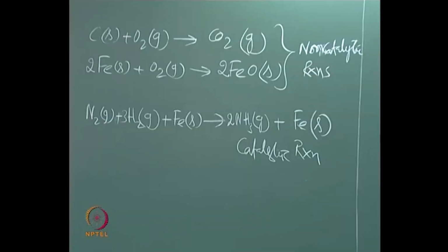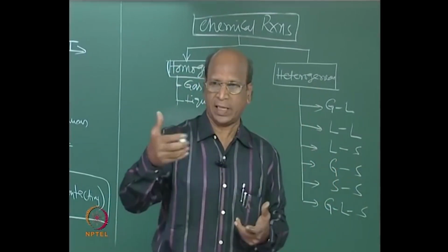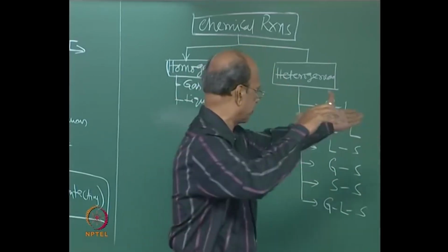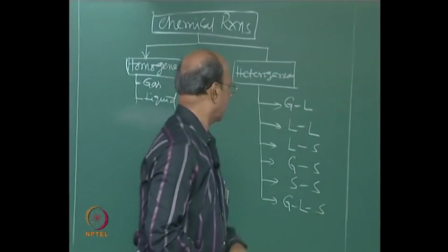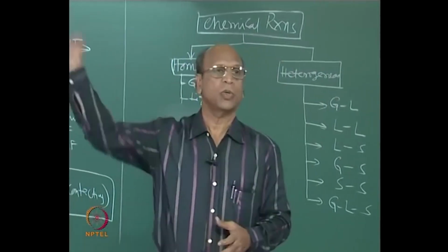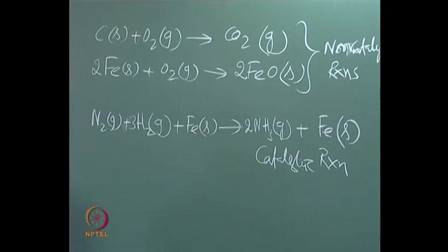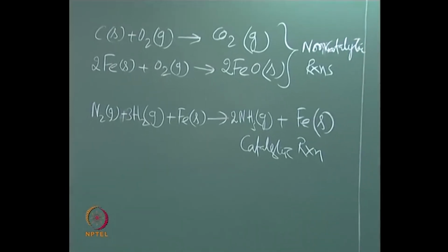So this we have to first identify, because the design of a catalytic reaction is totally different when compared to the design of non-catalytic reactions. But here a catalyst is there. One of the examples we can give is the packed bed. For ammonia, they always use packed beds only. All the iron is loaded in this reactor, and then hydrogen and nitrogen are sent continuously. So you will get continuous production, and most of the time the catalyst will not get deactivated. If you do not have deactivation of catalyst, you can run it for a lifetime.